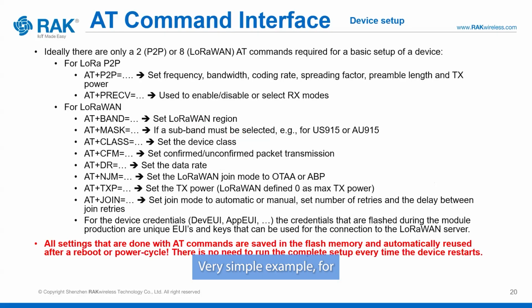Very simple example for device setup with the AT command interface. Actually, when using LoRa P2P, only 2 commands are required. For LoRaWAN, it's a little bit more complicated. You need around 8 AT commands. This is the very basic setup.